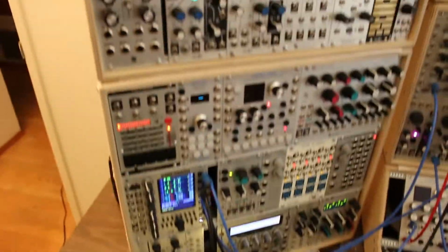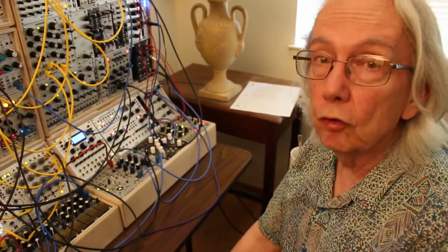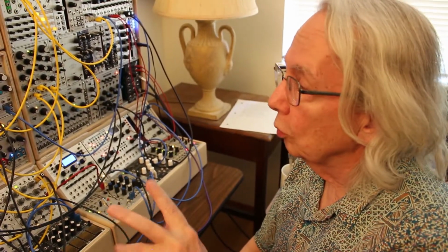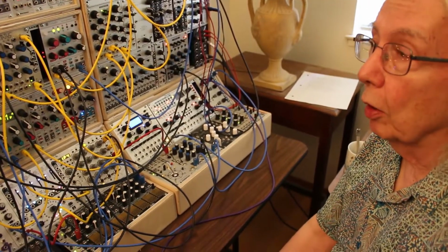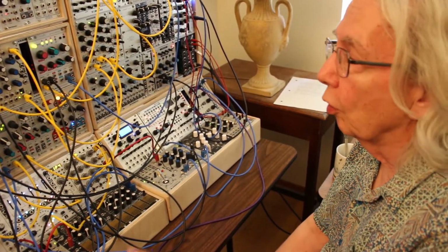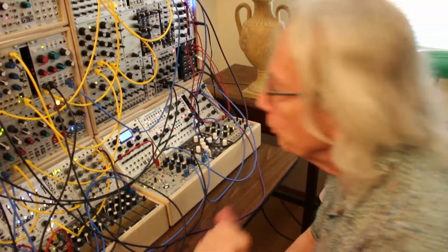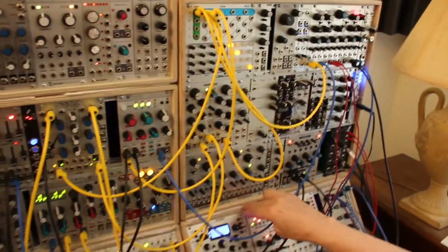One of the things that people need to know about, of course, with modular is the power supply requirements. Anytime you've got a bunch of modules in the case, you need to check and read the manual for each of them and then add up the amount of power that each of them requires and make sure you're not overloading the power supply. Now, when I first bought this case, you'll observe that this case has 3 tiers instead of 2.